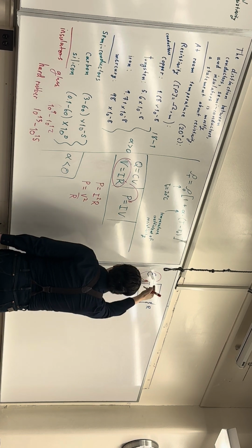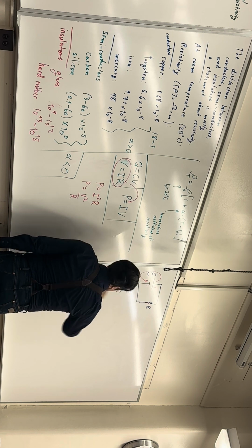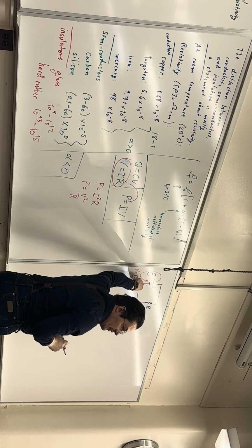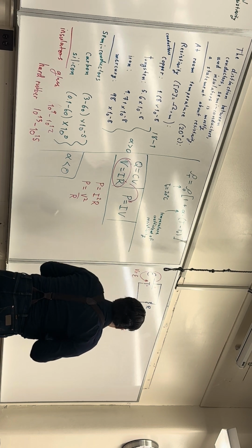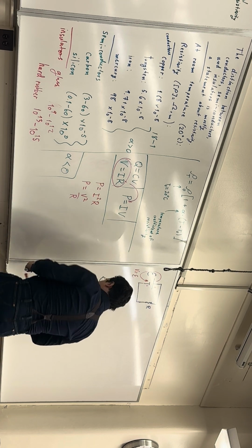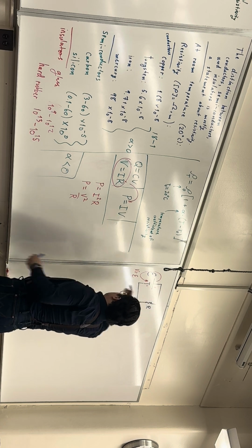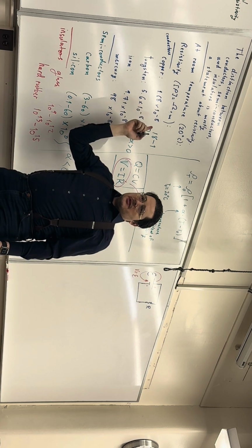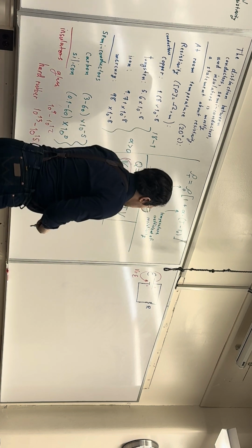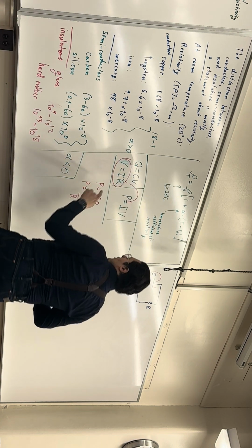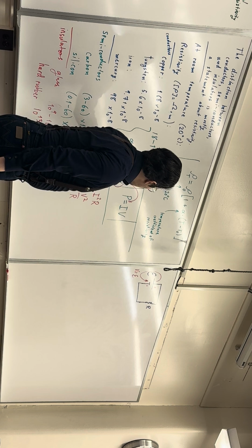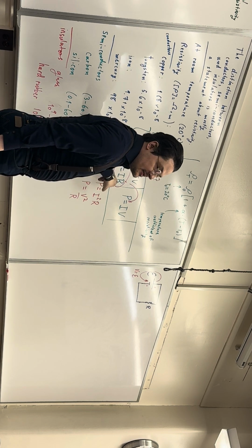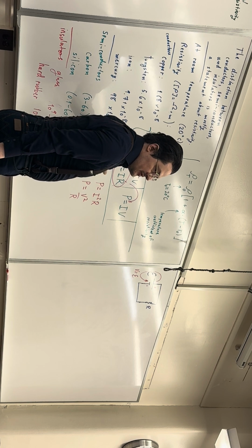Okay, and because of these lines here, this is positive and this is negative. So this top plate is curly E higher in voltage than the bottom plate. Now, this copper wire here is a conductor. It has some resistivity, it's very small. But if we look at Ohm's law for the copper wire, if there's any amount of current flowing, as long as it's not too big, and the resistance is really small, the voltage difference is small.